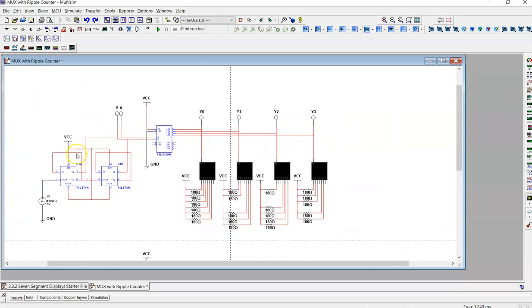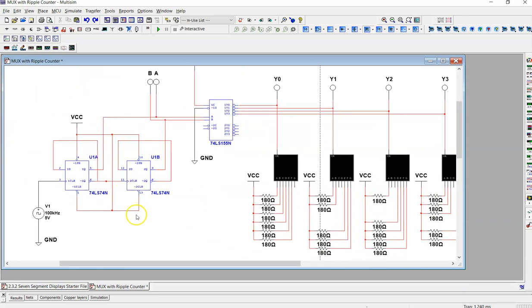Okay, so the ripple counter, you can kind of take a look at and copy this as well. It's the 74LS74N. You're going to find that in the same place, just further up since it's a lower number. And you'll kind of notice, right, I got the clock signal going in, the inverted value output of one flip-flop becomes the clock signal in the next, also becomes the next data value. So we kind of loop that inverted output Q back to D, the data pin. Q is our output, and Q is going to be our binary count.